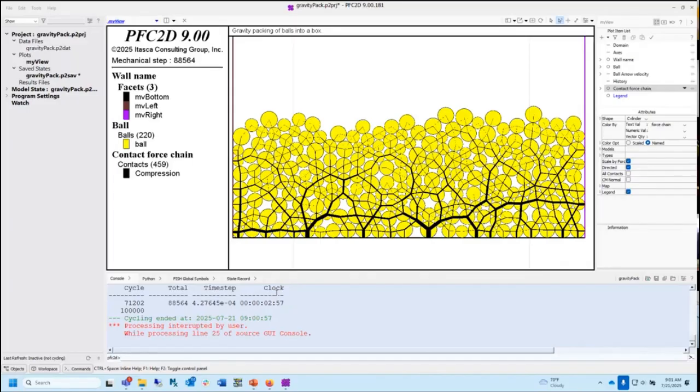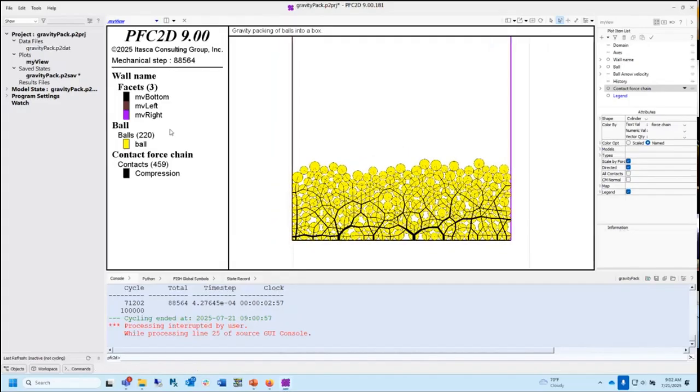And then you should try to build the specimen in the same way you do in the laboratory. So if that means you were pouring it in from 500 millimeters above, you should do the same thing with the model. And then the model will achieve whatever state it wants to achieve. Does that make sense? Yeah. Okay. And you could play games with things, but let's not even worry about that. Yeah, that's what you should do. Okay. So are we good? Is this making sense?